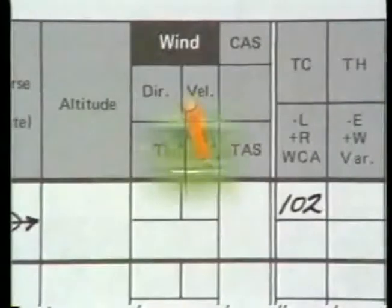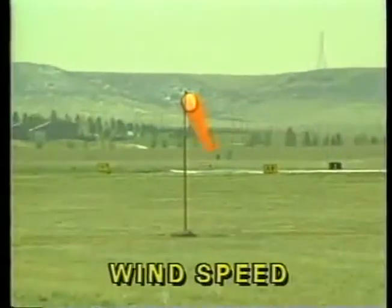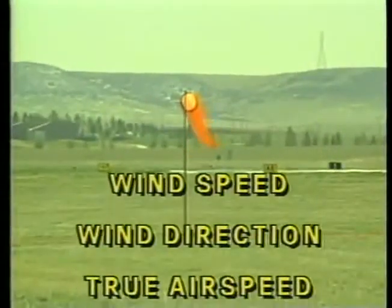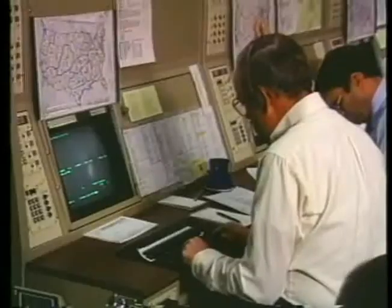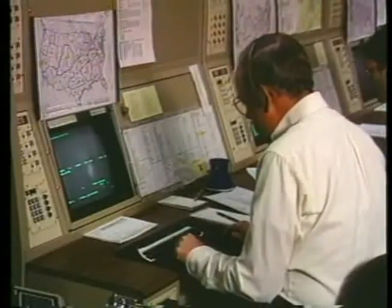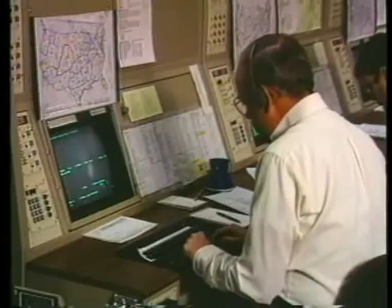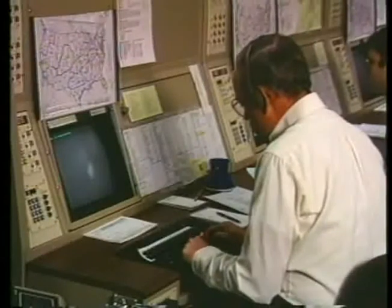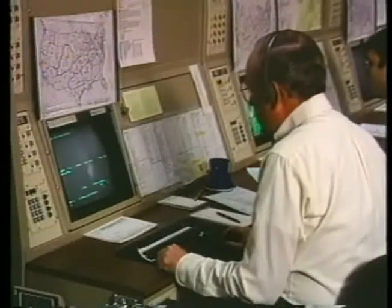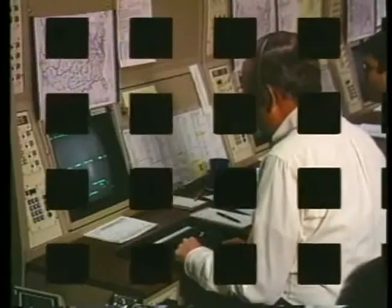The next planning step is to analyze the effects of wind. Here you need to determine the wind speed and direction and the true airspeed. With this information you can find true heading and ground speed. You can obtain the wind information during your normal pre-flight weather briefing with the flight service station. Wind and temperature at 3,000 are forecast to be 240 at 16 and temperature 23. At 6,000, 230 at 20, temperature 17.